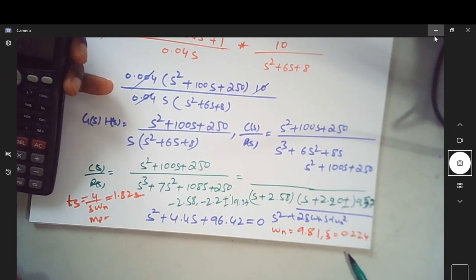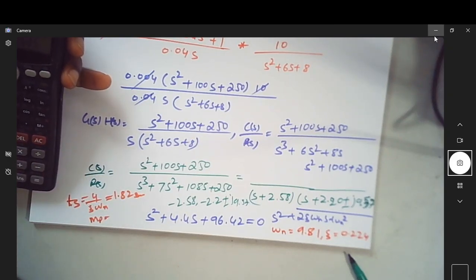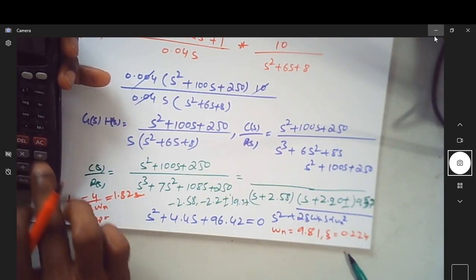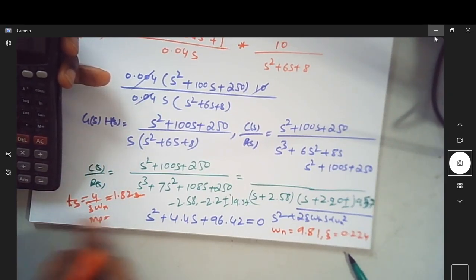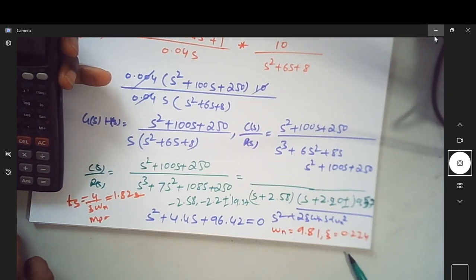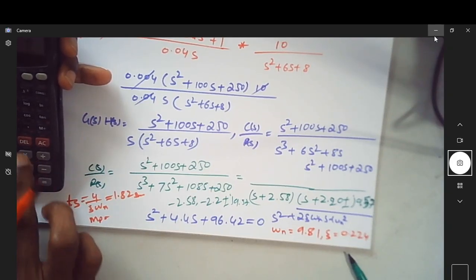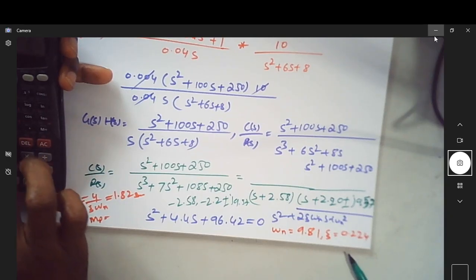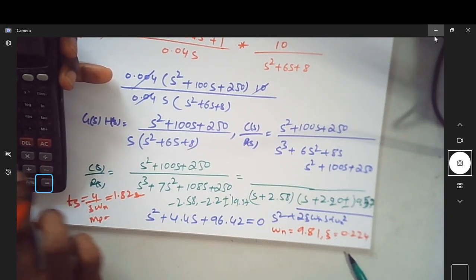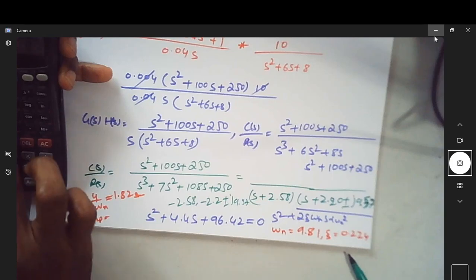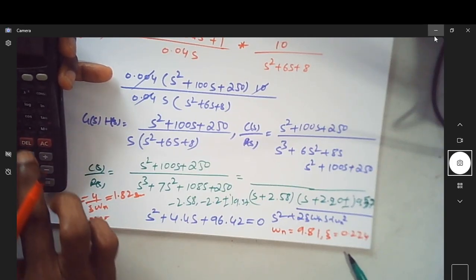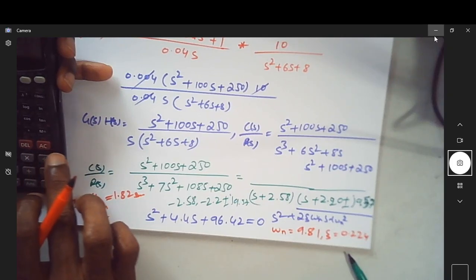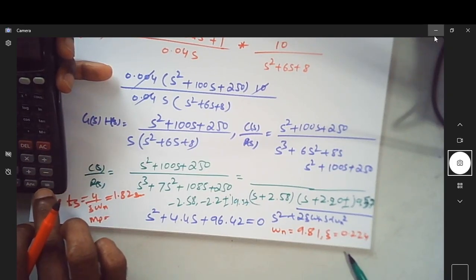Whereas what is Mp? Mp is exponential to the power of minus 0.224 into pi divided by the square root of 1 minus 0.224 square. I think I put in one extra parenthesis. Let me delete that.